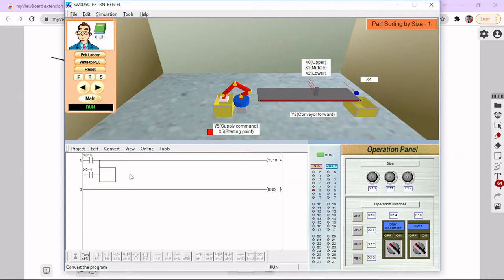Another thing I want to show here again is what we call precedence. Precedence in the sense that if you want a particular contact to control the operation of a particular rung, that contact is shown on the rung to have precedence over the inputs that you would want such a contact to have precedence over.